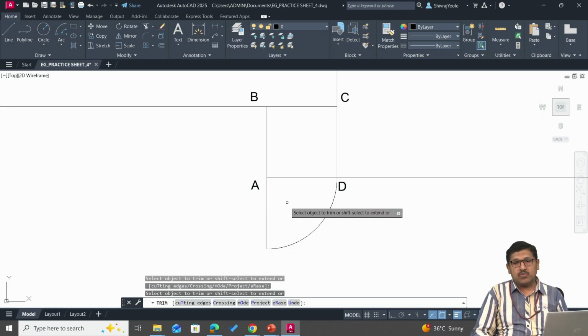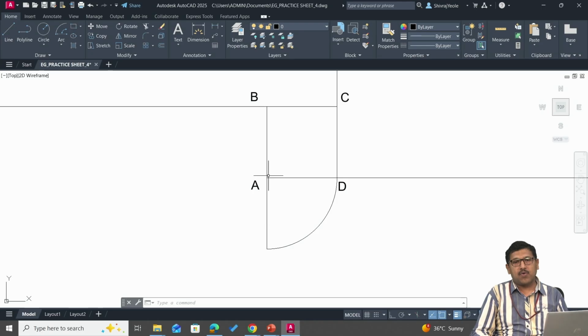Now what I need to do, I need to unwound the next length of the thread, which is the next side. So that means AB is the next side, and we have already unwounded AD length. So that means this is one side length and this is another side length. So what happens in the case of involutes of polygon, when we try to unwound it, for every step one side length gets added up. So in the first step we just unwounded one side length. Now in the next step we will be unwounding two side lengths. This is the AD and AB is the another side length.